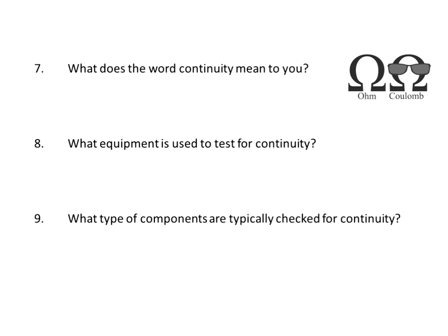If you look at your meter, you'll see on your meter you have a beeping function. When you use that beeping function on the meter, that's called a continuity tester. But also a continuity tester could be using the ohm meter on a very, very low ohm scale. So what does the word continuity mean to you? It just means there is a circuit connection between 2 points.